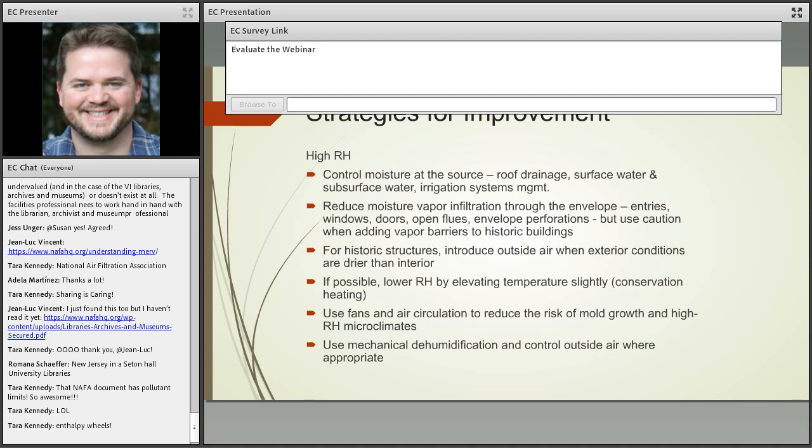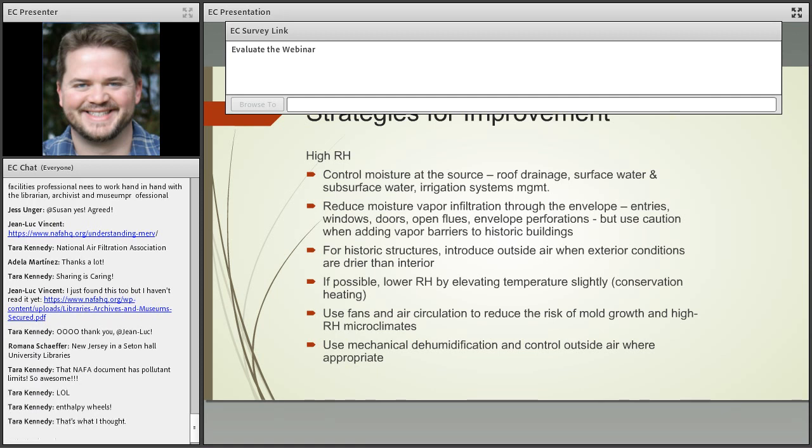We actually do just see this process where we're moving a little bit of heat from one side of the airstream to the other in order to help out in the right location. So wheels are not always going to be superheated depending on the application. There are scenarios where we could just use a standard heating coil, or oftentimes there might not even be a heating coil.